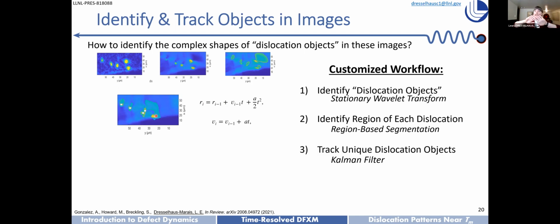And now what we find is, of course, that in many cases, some of these dislocations and their deformation fields actually overlap partly. This makes sense, though, because from elastic theory, we understand that the way that dislocations interact is via their deformation fields. So in all the places that the dislocations are doing some of their most interesting things, they will actually be apparently overlapping in this picture.